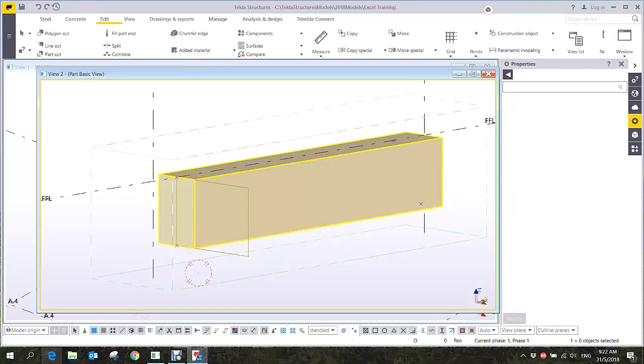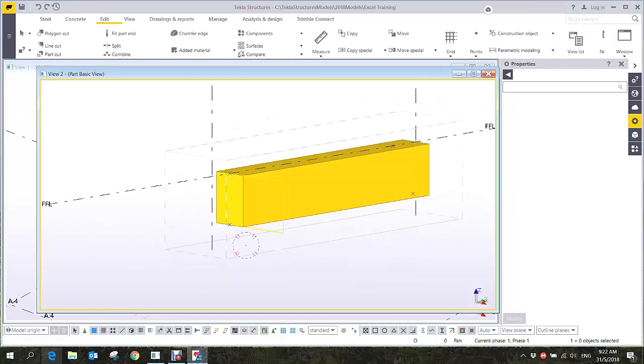Any advantage for this? Yes, of course. There's a lot of advantage for this one. This one will be used for your detailing. Because let's say, for example, you model wall to wall. When you model, it's always 0 to 0, right? So to enable you to have a gap, you cut that one instead of moving the handle.